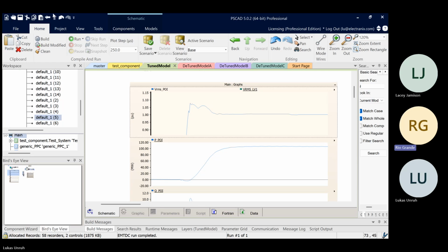During the fault, the phase lock loop, there's no voltage to measure, right? So it's kind of frozen to a degree. And when it comes out of the fault, it's going to have to resync to the grid again in some respects.